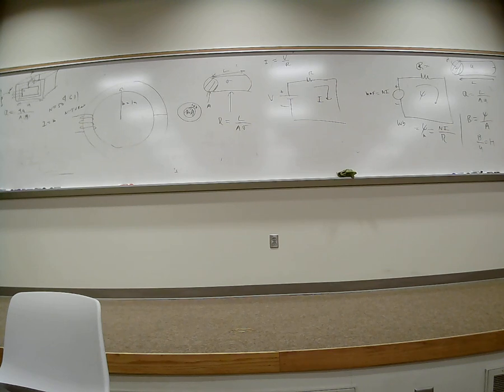The current is proportional to the magnetic flux. Now he uses phi for magnetic flux. I usually use psi, it's more common that way. And the resistance is directly analogous to reluctance. V equals IR, or Ni equals magnetic flux times reluctance, and mu is just like sigma. Can you all follow the parallels?